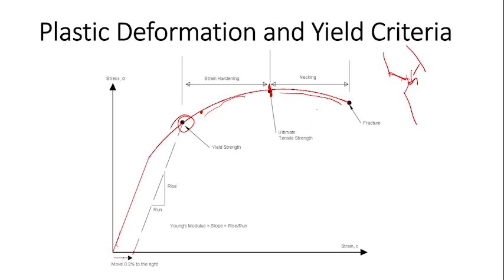After ultimate tensile strength, this will not be uniform. At some location where your material is weaker, a significant amount of area will be reduced. The way she said, that is correct. Then that is what we call necking. After ultimate tensile strength, at some position the area will start decreasing significantly or abruptly. Okay, till here there will be gradual plastic deformation, but after reaching ultimate tensile strength, abruptly somewhere your area will decrease. That phenomenon is called necking.